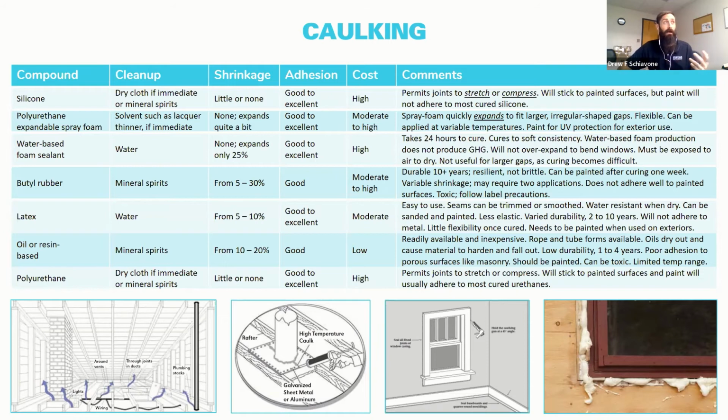And that spray foam typically comes in aerosol cans, and it expands and fills the gap. It's not going to fill a huge space, but if you're talking 1/2 inch or more, it may work well with that. And for any product that you look at, you want to look at the labels. You want to see if you're using it in a moist environment, if it's moisture resistant. So a closed cell foam would be beneficial for a moist environment. A closed cell foam will stop moisture and air infiltration, and also provide some insulation level as well. So that's what you see around the window in the bottom right, is some spray foam that's filled a larger gap.